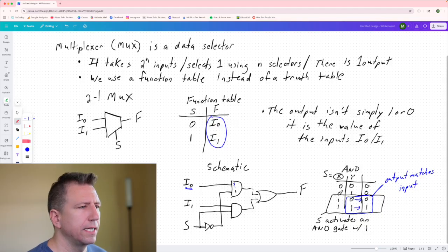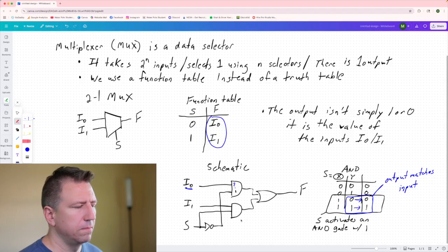And on the other side, if we give a 0 for the S to the AND gate, then it's always 0, so nothing happens here. And so when that gets fed into the OR gate, it doesn't say anything. It's just a 0, and the 0 plus an OR gate is just the OR gate itself, right? So we look at the other side. So that's how this works.